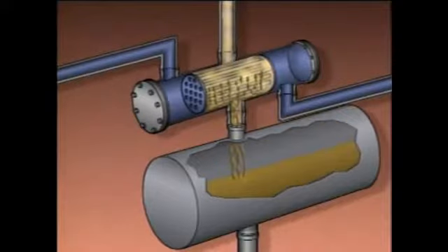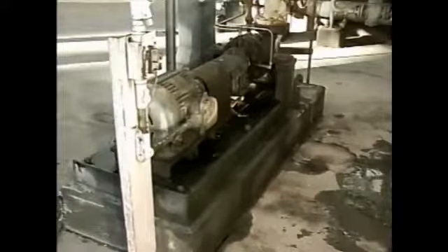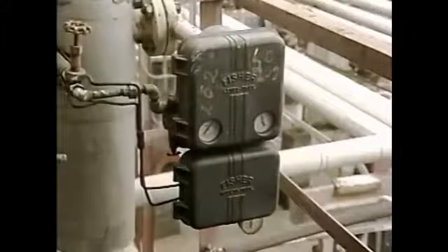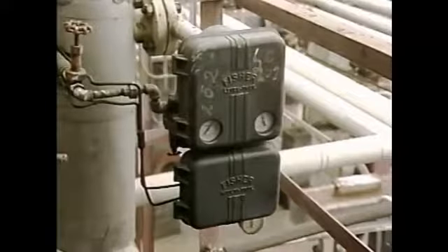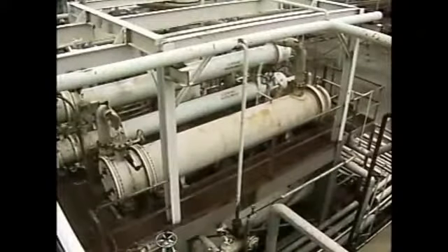If the level in the receiver gets too low, equipment located downstream of the condenser could be damaged. For example, if the receiver level gets too low, the pump that's used to pump distillate out could cavitate. The cavitation could prevent the pump from operating properly and damage the pump. A controller on the receiver automatically maintains level. An abnormal level could be an indication of a problem with the controller. A low level could also be an indication of a problem with the cooling water flowing through the condenser.